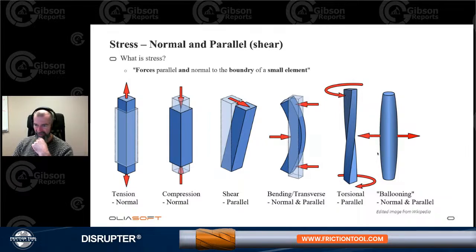Here is an illustration of how it actually looks. So if you do have higher pressure on the inside compared to the outside, the walls will start to balloon. And obviously it could be the opposite way in some cases. Well, a case came to mind where this can happen: if you're running a string into the hole, and obviously in most cases you're not just continuously filling the drill string.